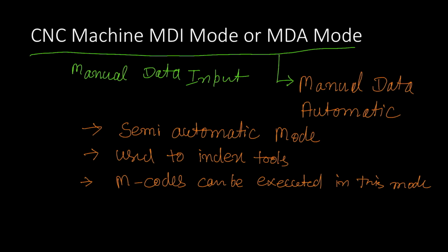Second, both provide manual capabilities that can also be done in a more automatic way. In edit mode, the operator can enter CNC programs into the control memory. This can also be accomplished by loading the program from some outside device such as a computer or tape reader, or, in modern CNC machines, a pen drive.